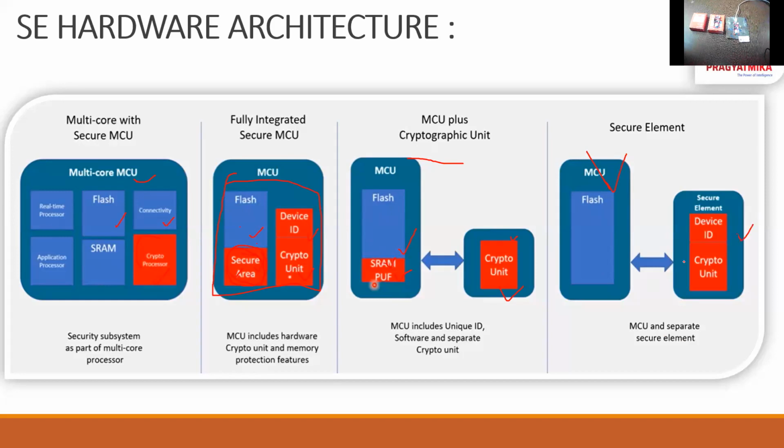And whenever data has to be sent from the MCU to the radio unit, we have this WINC controller, the radio controller for communication over Wi-Fi. So whenever this data has to be sent through the WINC controller to the cloud, it will be signed by this secure element. The JWT tokens will be signed by this secure element, and all the information is stored in this hardware. And that is unique. Every IC that is manufactured is unique.